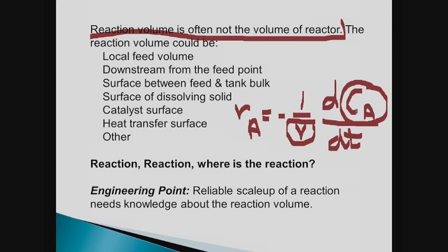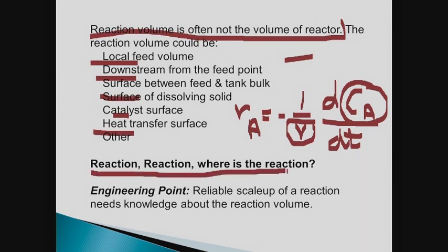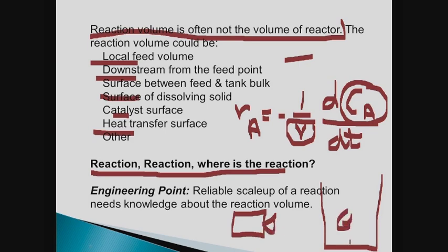If you remember the static mixer where you're mixing red and white, there's a whole bunch of places where reactions can actually take place. So my favorite question whenever I deal with scale-up of reactors is: where is the reaction? And I would very much advise you to videotape with a camera whatever is happening in the lab so you know where the reaction was.